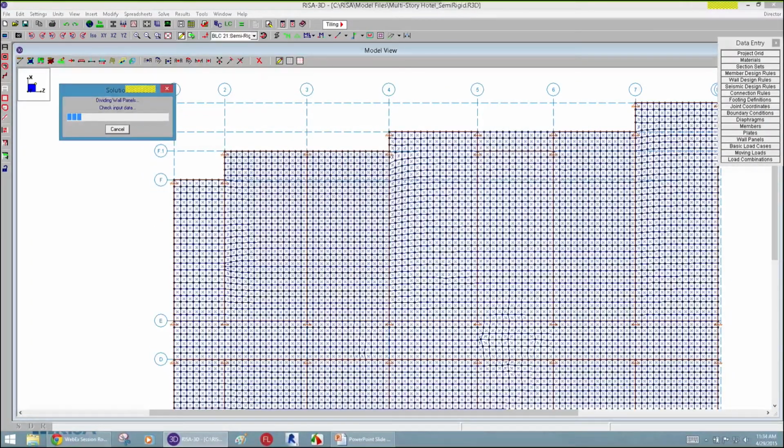If you're not familiar with the batch solution in the envelope, this is newer in the last couple of years. What we did was we added the ability for you to run not only just a single combination, but a collection of those, which would be the batch solution, and also we would envelope all the forces for you. And in a model like this, it's going to take us just a few minutes to run this model. So it would be really beneficial for you to be able to get the minimums and the maximums out of an envelope solution, and then also be able to drill down and get the single combinations where you need to do more of the design information, like looking at a shear wall. You really need to know more things like what's happening on a single combination. So the fact that you can run all those at the same time is really, really helpful.